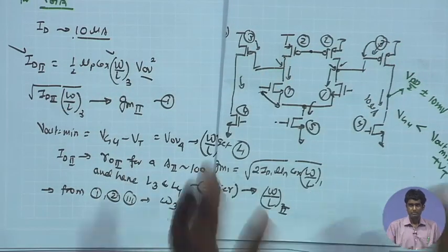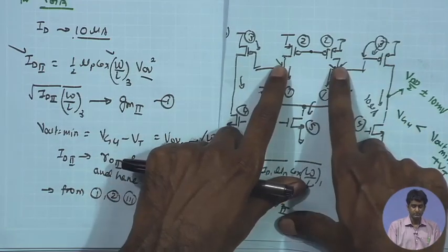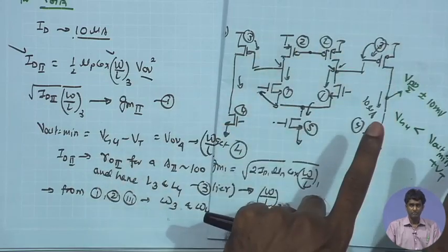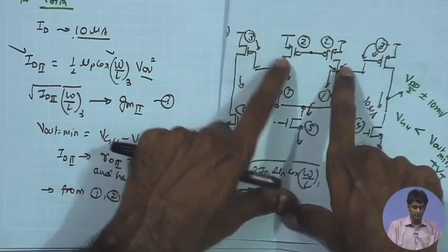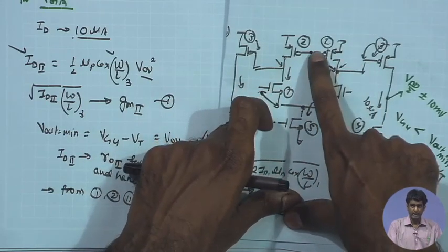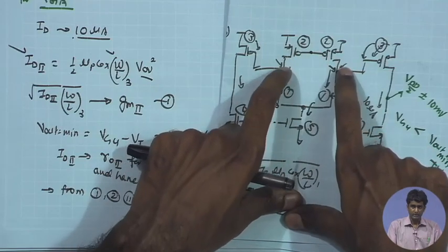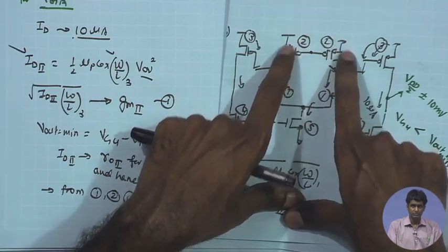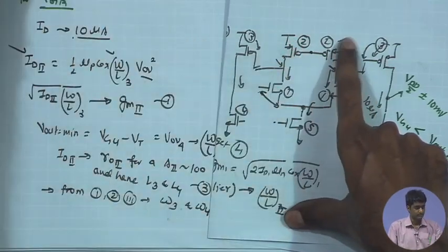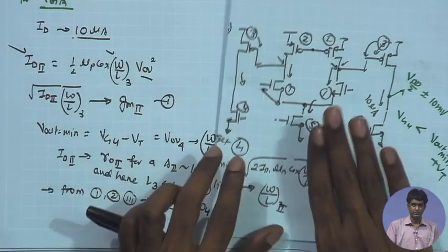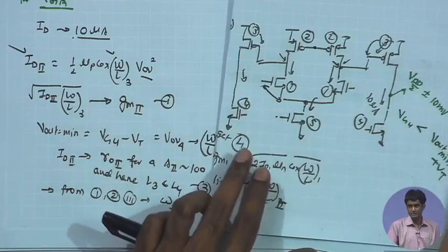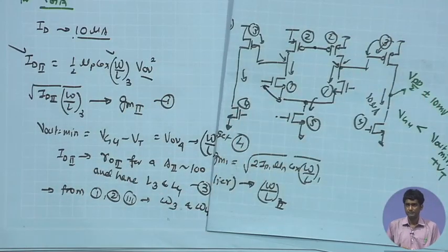Remember, in the common mode feedback that we have studied, how did we bias this? If you are going for a separate loop, it is biased with the help of a common mode feedback amplifier with reference equal to the Vg of this MOSFET. And in this case, since we are expecting a larger DC potential over here, we would like to have the Vg over here also higher, and that would require a larger W by L. So, that is the difference with respect to the earlier case. Some of the constraints get relaxed and some other constraints come in to determine the overall sizing.